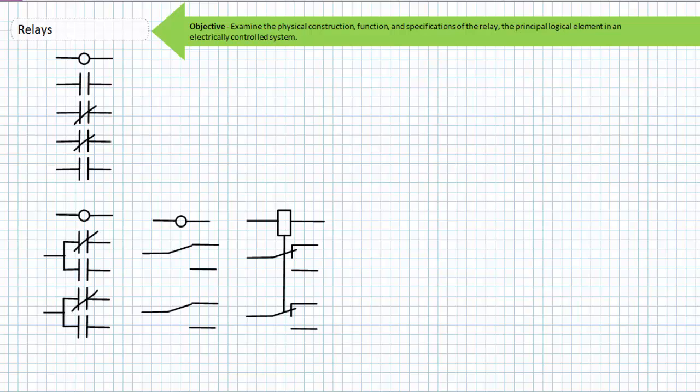For this schematic symbol of an industrial mini contactor relay with 4 electrically isolated switches, 2 of them being normally open and 2 of them being normally closed, this is the first switch. Each terminal of this specific switch is assigned the first digit of 1. The second digits indicate the function of the switch. Normally closed switches are assigned a 1 and a 2. Normally open switches are assigned a 3 and a 4. Since this first switch is normally open, these terminals will be 1-3 and 1-4.